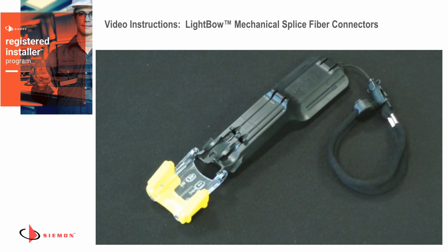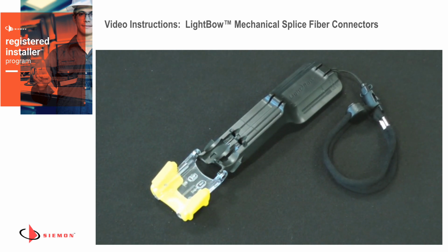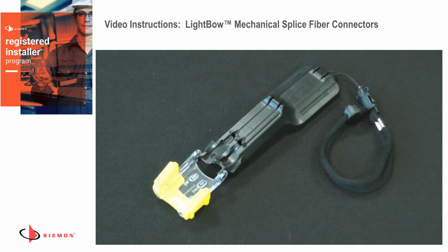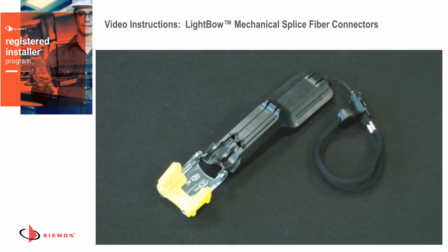Lastly, the tool should be free of dirt and debris and should be periodically checked for wear, specifically the termination fins present in the clear plastic cover, as this will affect the tool's ability to terminate the connector correctly.